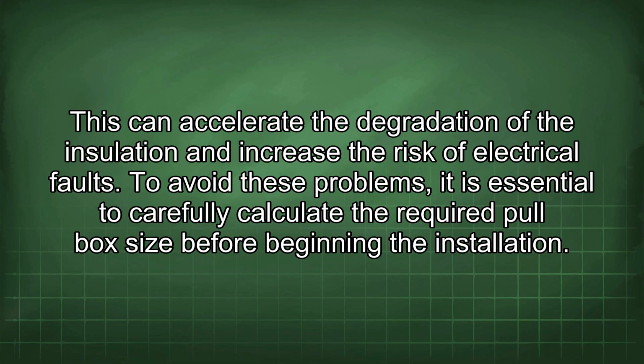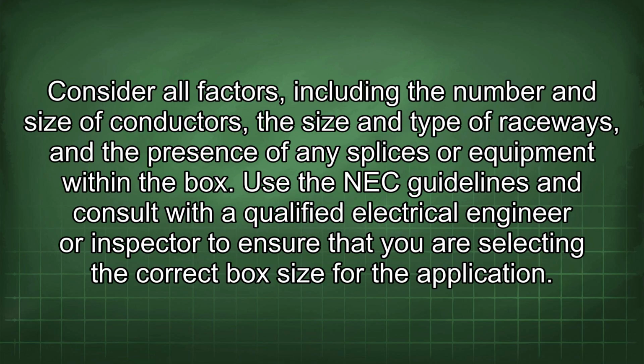To avoid these problems, it is essential to carefully calculate the required pull box size before beginning the installation. Consider all factors, including the number and size of conductors, the size and type of raceways, and the presence of any splices or equipment within the box. Use the NEC guidelines and consult with a qualified electrical engineer or inspector to ensure that you are selecting the correct box size for the application.